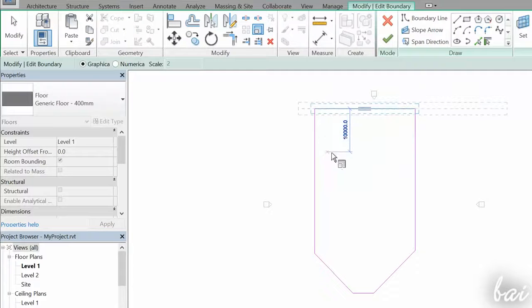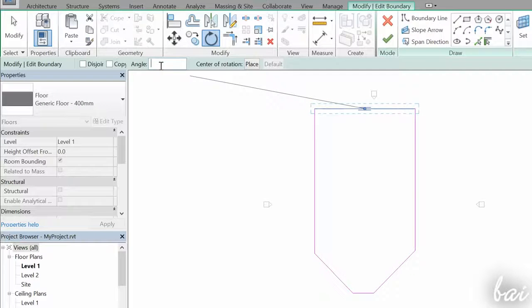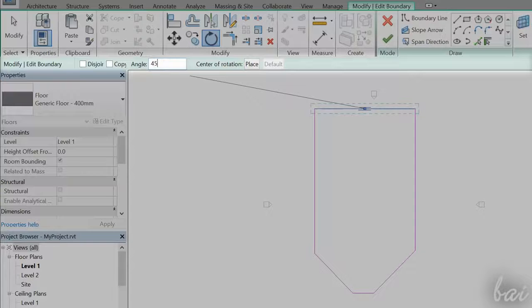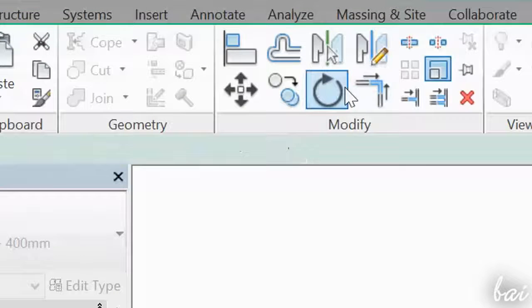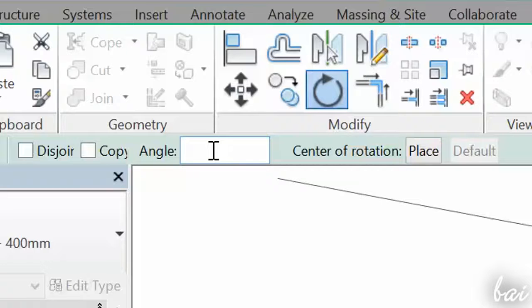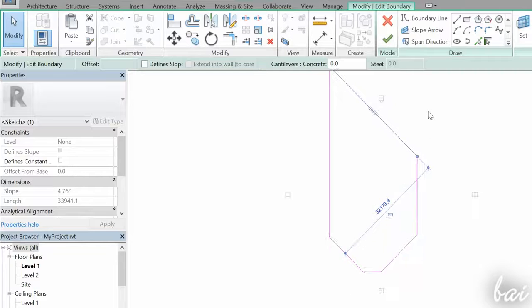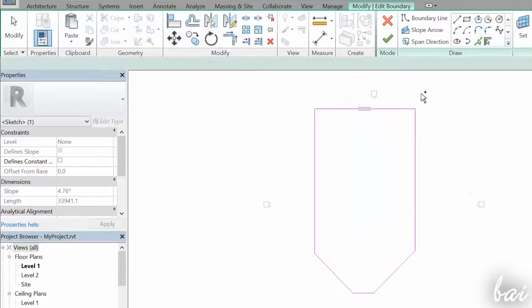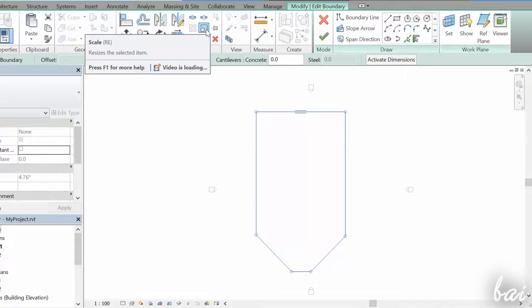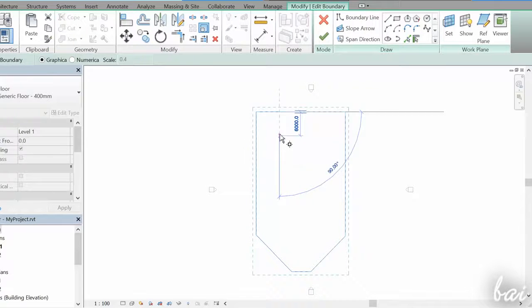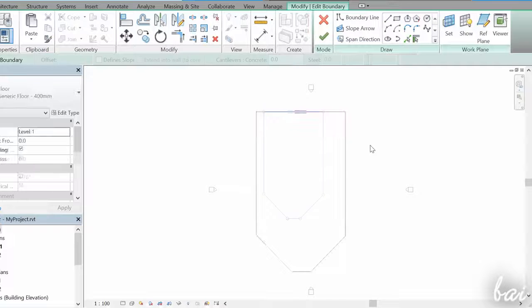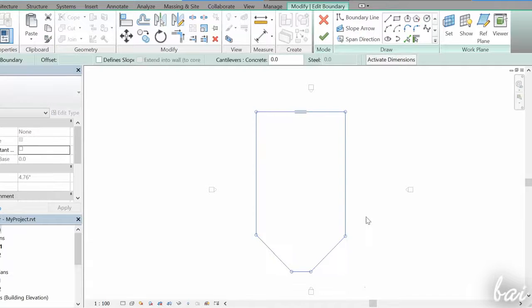There are many other tools inside the Modify section. Check them. For each editing object, you can adjust its settings through the options right above the workspace. Type inside with your keyboard and use the Enter key to apply. If you make mistakes, use Ctrl and Z to undo your latest action. You can also apply these tools to multiple sides in the same way, always using the Modify tool. Just click and drag on your workspace to create a selection area that will select all objects inside it. If you need to deselect, just click outside.